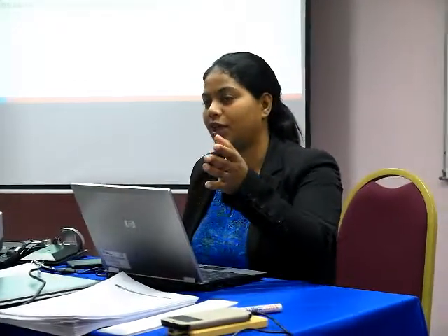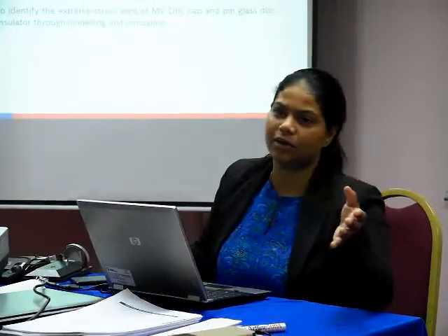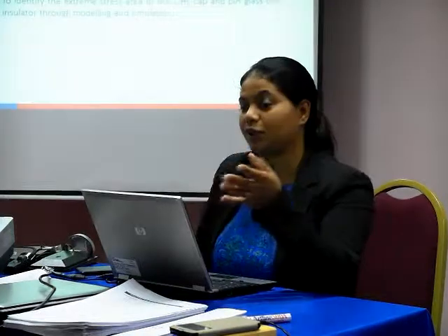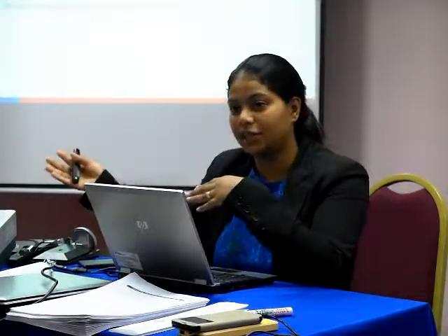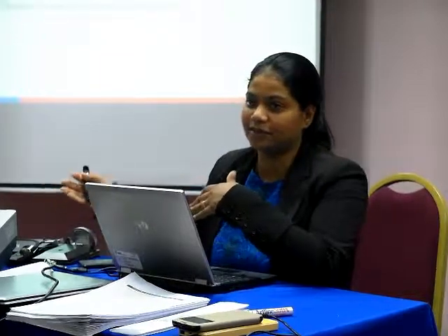So when we go to site, when we capture, okay, this pin insulator is emitting this amount of discharge, and then we see, okay, this is a 3 to 5 years insulator, and now it's only emitting this amount of discharge. So we will be able to predict what is the lifetime or how severe is this cap and pin insulator.